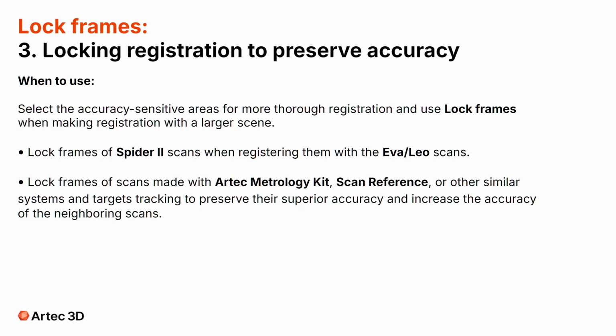This is also the standard workflow when using the Artec metrology kit or external targets. You log the scans that are already anchored to your high-accuracy photogrammetry skeleton. By doing this, you preserve that superior accuracy and force the neighboring scans to align to those fixed, reliable references rather than letting the whole project shift.